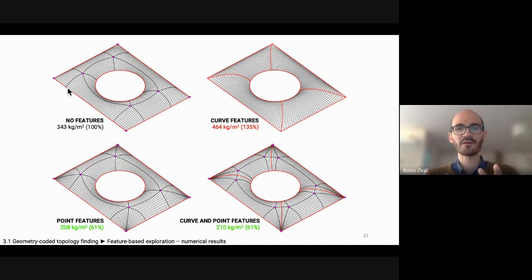You have this coarse quad mesh and this dense mesh, with a relation between the edges in the coarse and the edges in the dense mesh. So when you get this complex mesh with many singularities, you can still read it, apply rules to delete some strips to reduce the number of singularities, and change it in the dense mesh as well. So you have these two spaces of dense and coarse meshes that change at the same time.